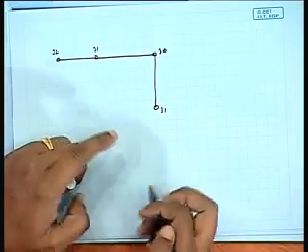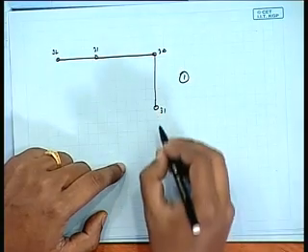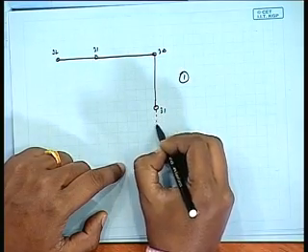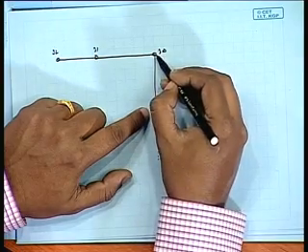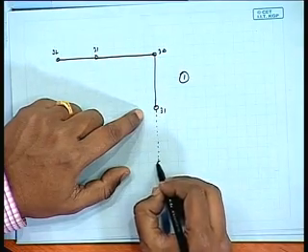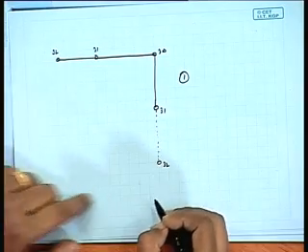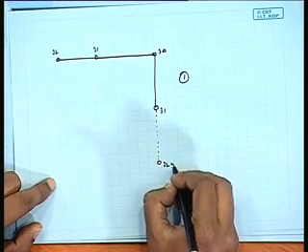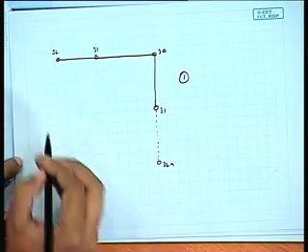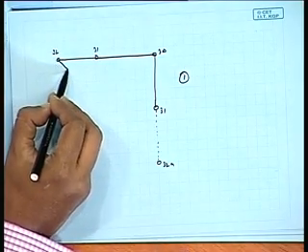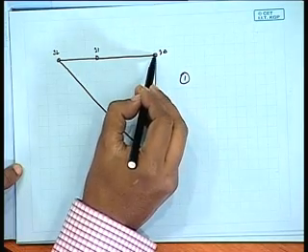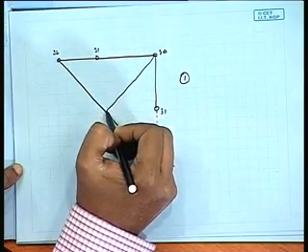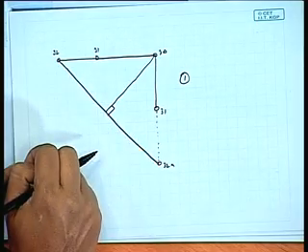There are two ways to do the procedure. One is, you can extrapolate this to almost the same distance at the 30th. So this is 32. Then you can connect this, and this becomes the equipotential line here. And then from here you can find the perpendicular and find the hydraulic gradient, isn't it?